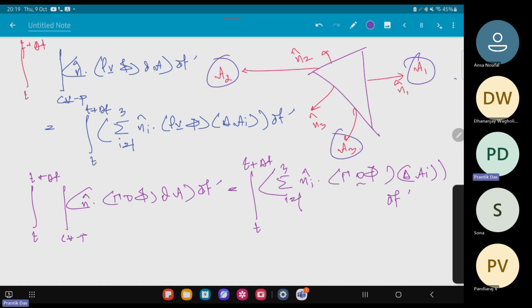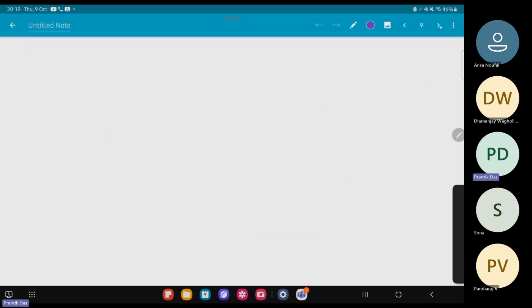I've shown you how to discretize the spatio-temporal terms which are present in the Navier-Stokes equation itself, or the general transport equation. But from now onwards, we will drop the time integrals, because we already know we can easily deal with them, as I've shown earlier in the implicit and the explicit schemes. Therefore I will now show you how to deal with the spatial integrals, which is actually one of the problems.